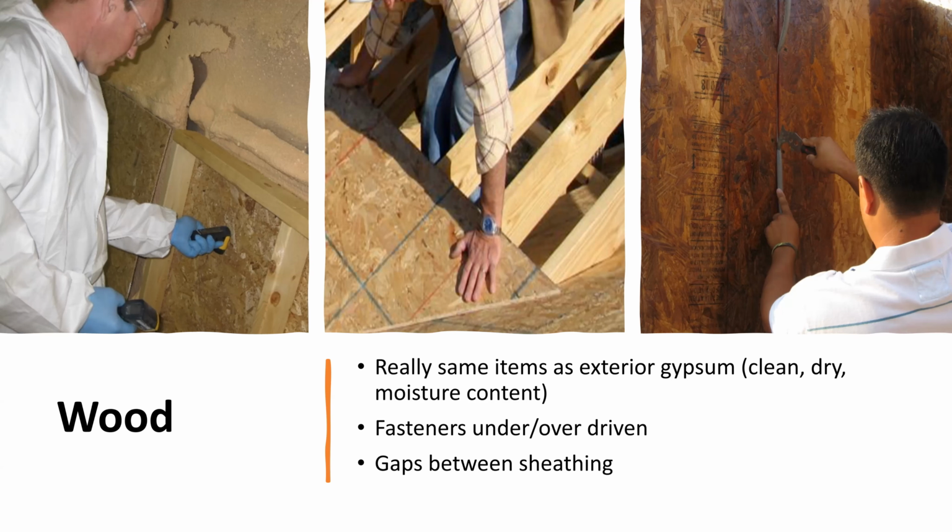Wood is one of the ones where they've said, listen, we're going to help you out. You can use a pin probe, and we're actually going to give you some direction in regards to it. Hey, 18 to 20% is acceptable.